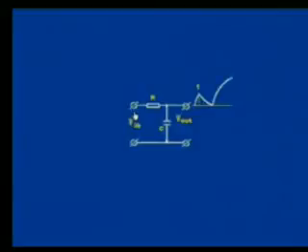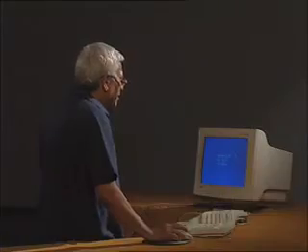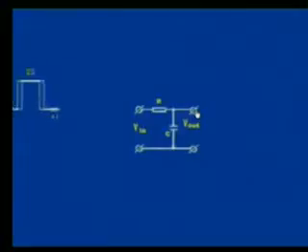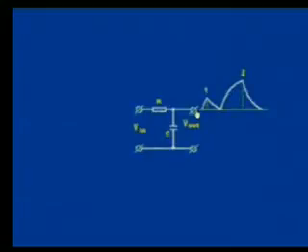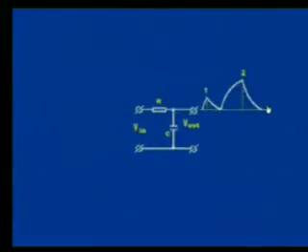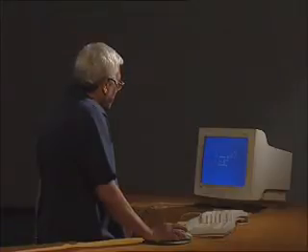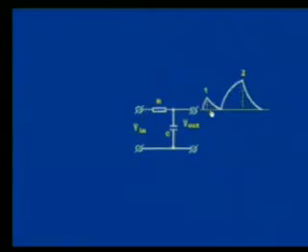As soon as this pulse enters the integrator, at the same time the integrated pulse is available at the output. See the fast movement, pulses are entering and immediately they are available at the output, because there is no delay. It is also clear the short duration pulses are making less amplitude compared to the long duration pulses.